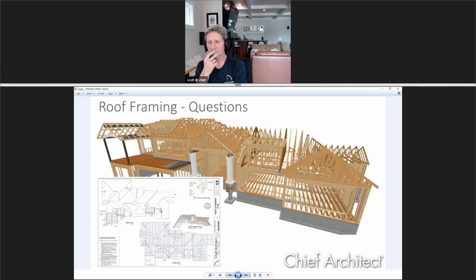They're reduced from 2x12s down to 2x6 or 2x4, and Chief does something odd when you check and uncheck the soffit box in order to view them. Sometimes you just end up with this open cavity you're viewing. It doesn't look quite right. So I'm wondering if X13 has got more features for this, without having to create a custom rafter tail, basically.